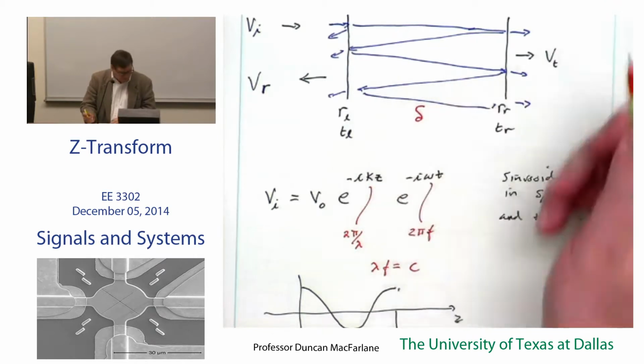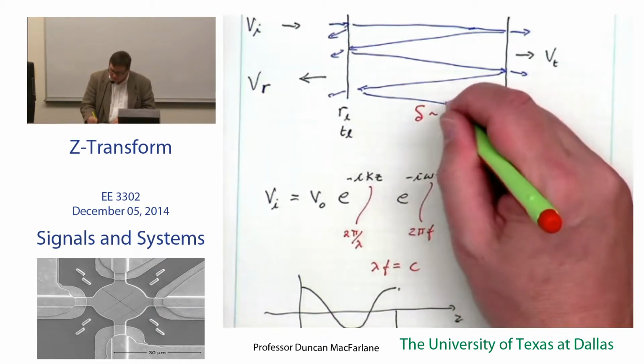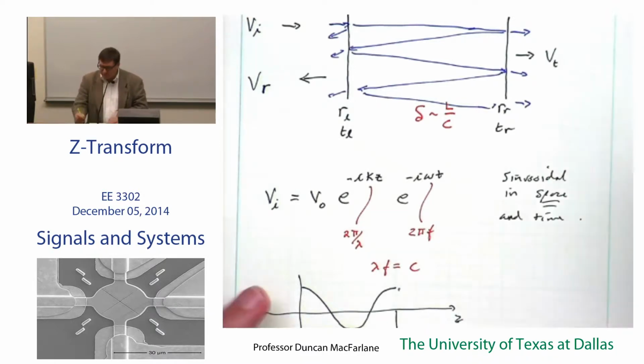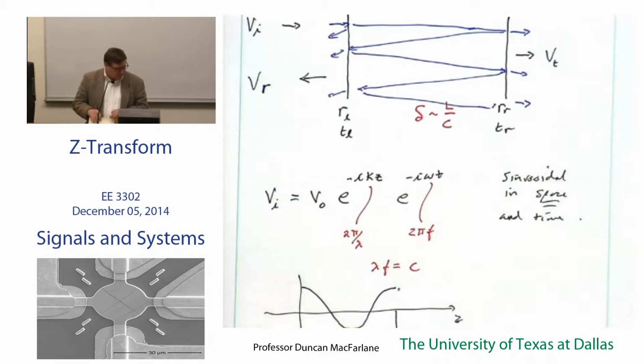My delay is going to be delta, which is L over C, the speed of light. So meters divided by meters per second, about 1 foot a nanosecond. So for whatever L is, say 3 feet, my delay is going to be 3 nanoseconds. A little bit longer because it moves a little bit slower through that polystyrene white material that's inside the coax cable. A little bit slower, but nothing that's really going to stress us out at this point.